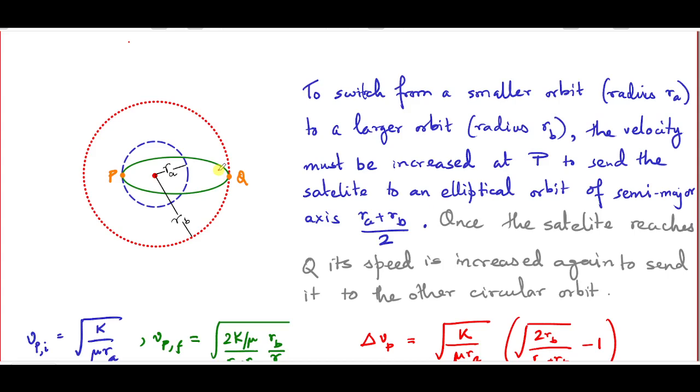So depending on various factors, you may or may not opt for a bi-elliptic transfer, even though it may lead to a smaller fuel consumption, because time may also be of essence. Of course, if time were really of the essence, like when you were trying to put men on the moon, you would not depend so much on gravitational transfer from one point to another, but keep the rockets on for a much longer period of time, ensuring that the overall time taken is reduced.